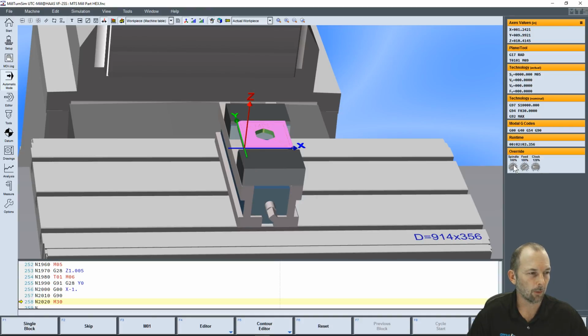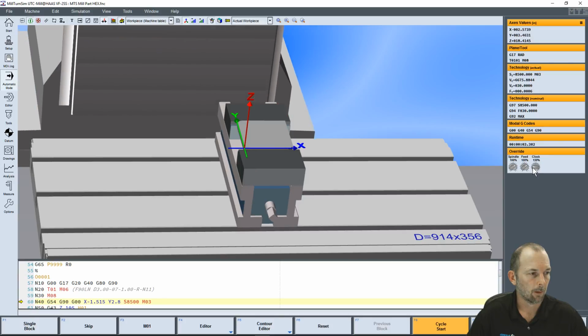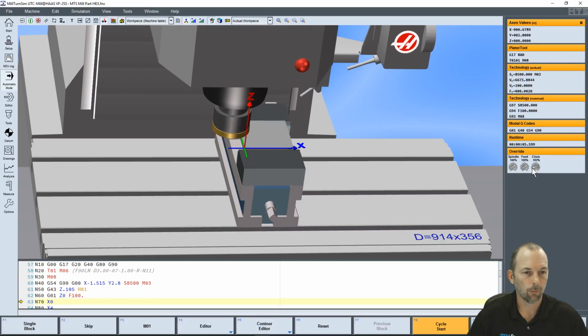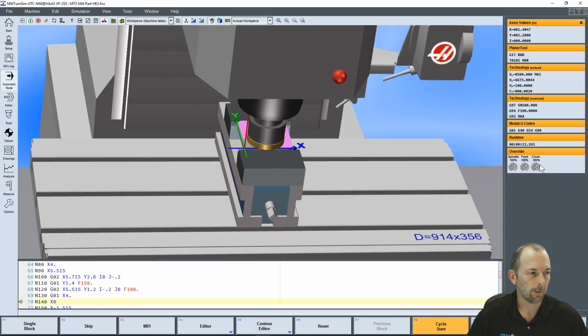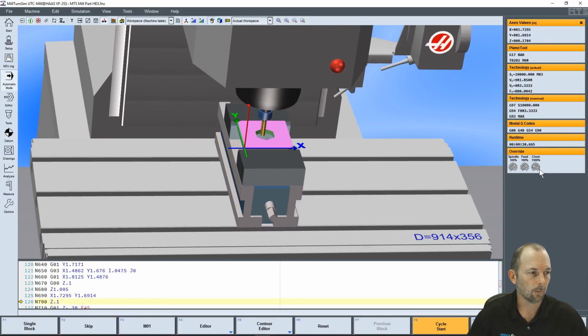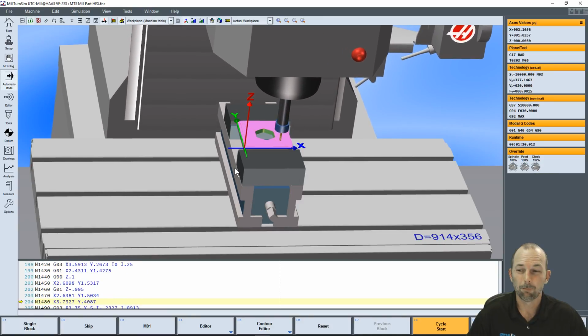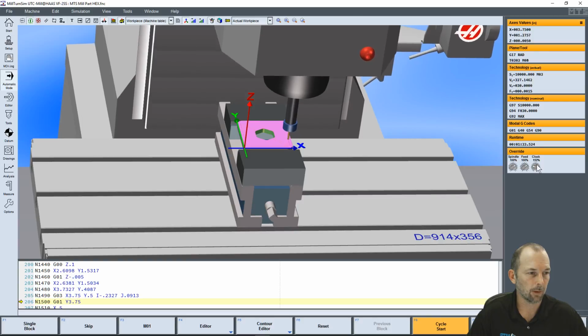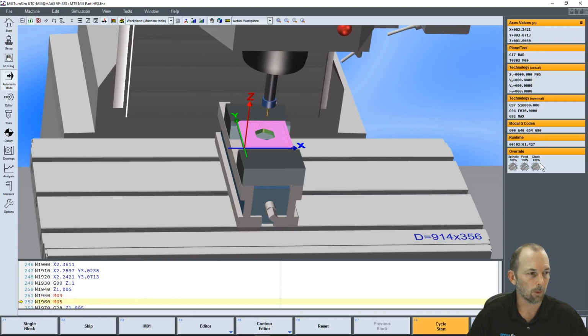The simulator has the same override buttons you would have on an actual CNC machine, the spindle and the feed rate override buttons, but we also have a clock override. So if I reset and I cycle start, 100% clock means we're traveling at real time. This is how fast we would see it actually run in the machine. We can turn that up. We can run it over 1,000, 3,000% of real time. If you have a 30-minute cycle on a part, you may not want to sit for 30 minutes and watch it simulate, so you can turn up time and move it along quicker.